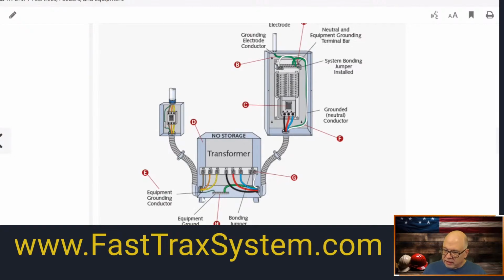You see it's coming in. And because the color scheme is not required, this obviously looks like 480 volts. But again, people think that brown, orange, yellow, or whatever is all required for 480. That is not true. That's not in the NEC anywhere.